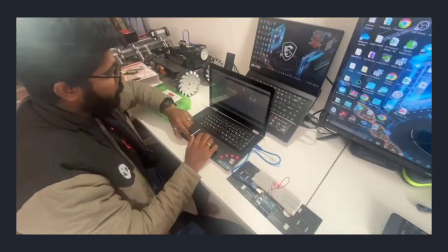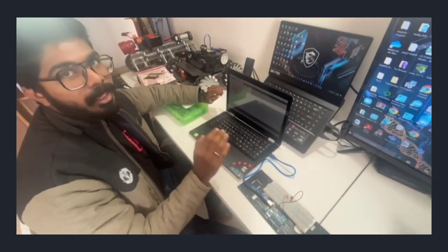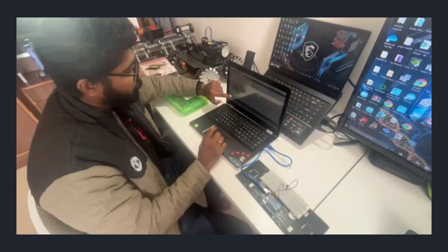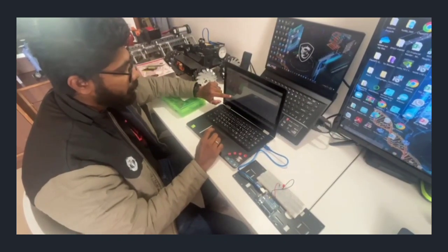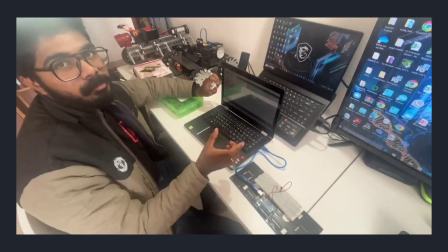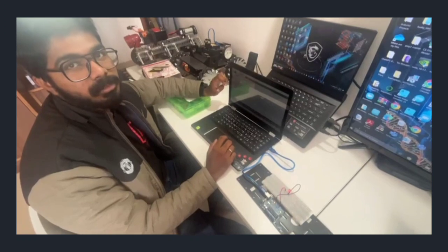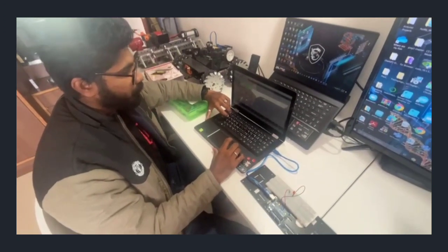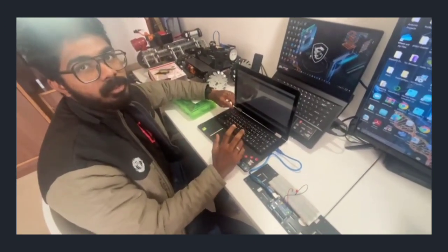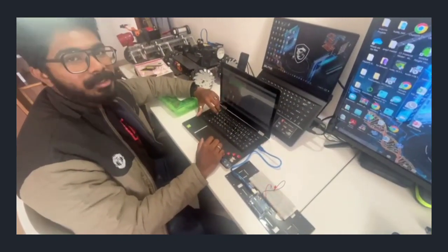Once it's SOS, we need a wait so that it gives a gap so that we can read the message. So we declare again over here delay long wait. As said in the starting, long wait has a 1 second gap. We can also make it 2 seconds by writing 2000 milliseconds. And anything you can change on the variables at the top. That depends on how we want the code. Exactly. Good work.